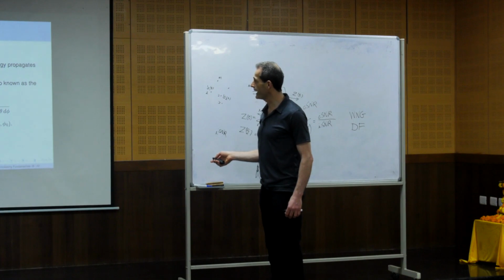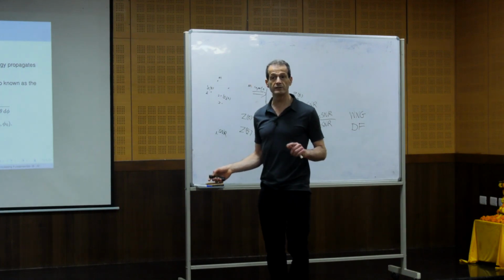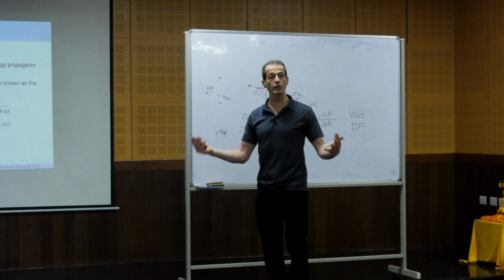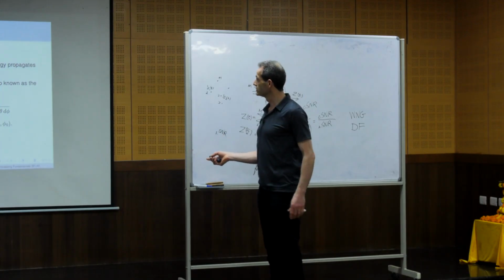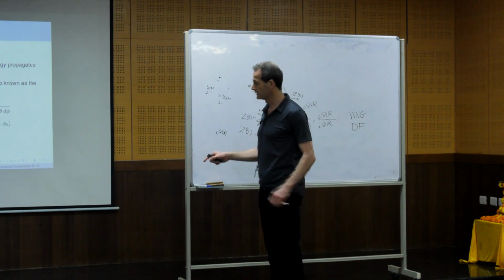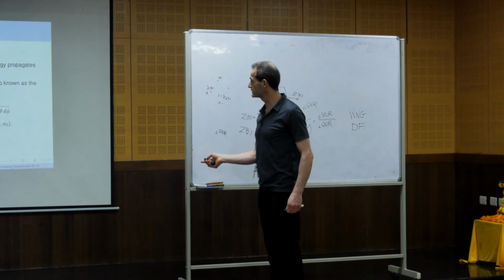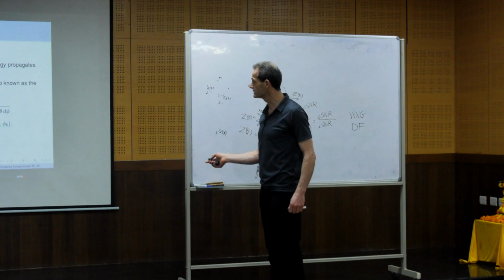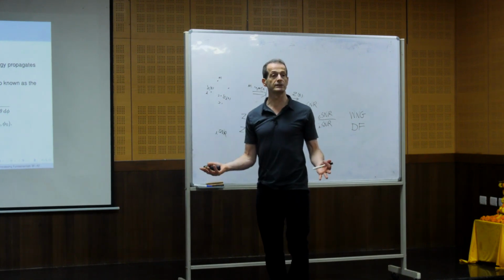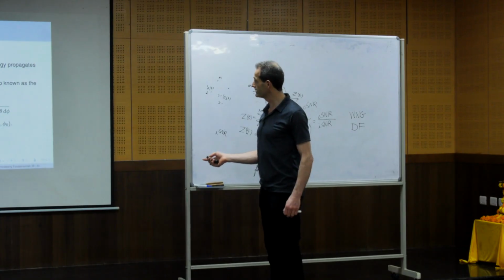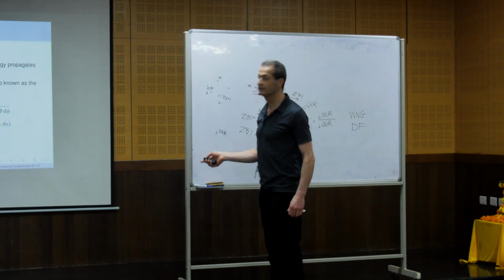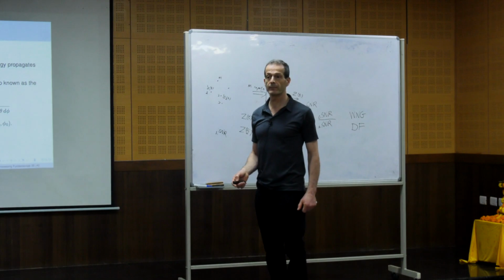And if we have diffuse noise, it comes from all directions with the same power. So if we take the integral on a sphere of the directivity pattern, the magnitude squared of the directivity pattern over all directions, what we get here, this is the gain for the diffuse noise. So we can define this as the directivity factor. Okay?